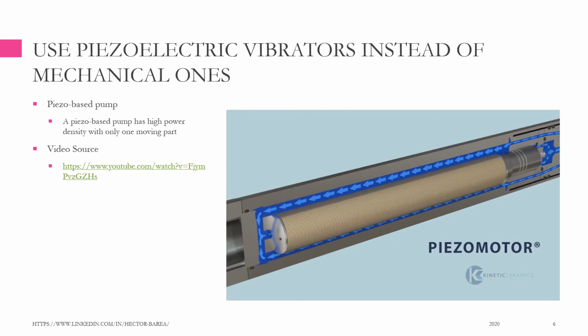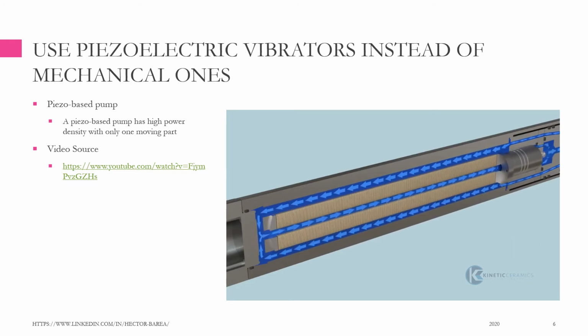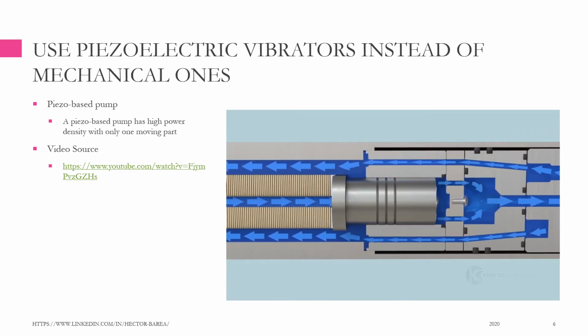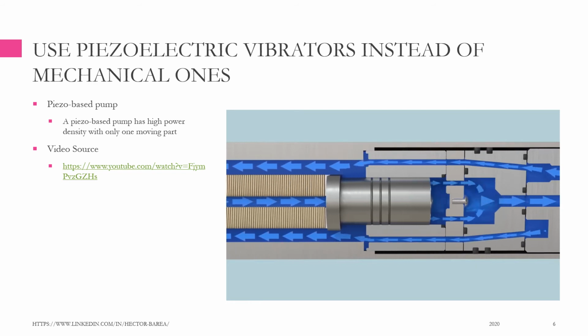As we look closer, the driving force behind our solid-state pump is our proprietary piezo motor, which is comprised of a stack of piezoelectric discs. In this pump, the piezo motor is immersed in fluid and can deliver pressures up to 10,000 pounds per square inch. This rapid, powerful oscillation forces fluid through the outlet valve.